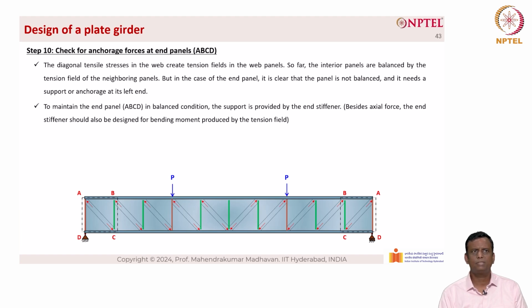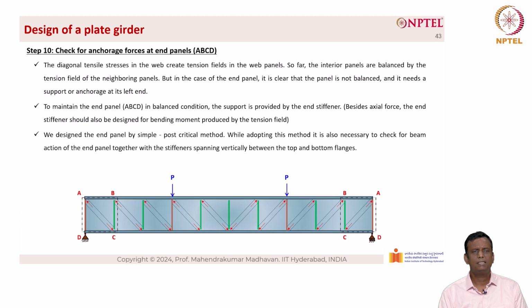Besides the axial force, the end stiffener should also be designed for the bending moment produced by the tension field. We designed the end panel by the simple post-critical method. While adopting this method, it is also necessary to check it for beam action of the end panel together with the stiffener spanning vertically between the top and bottom flanges.